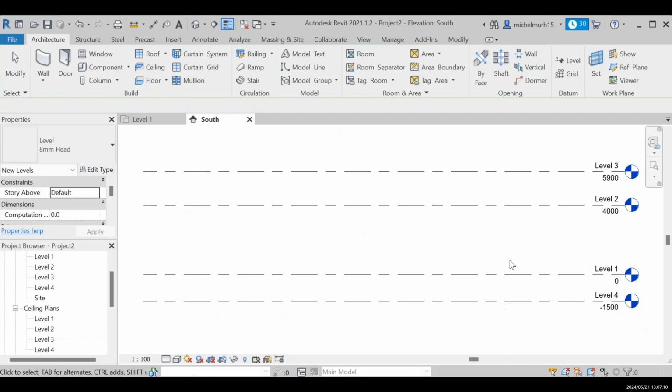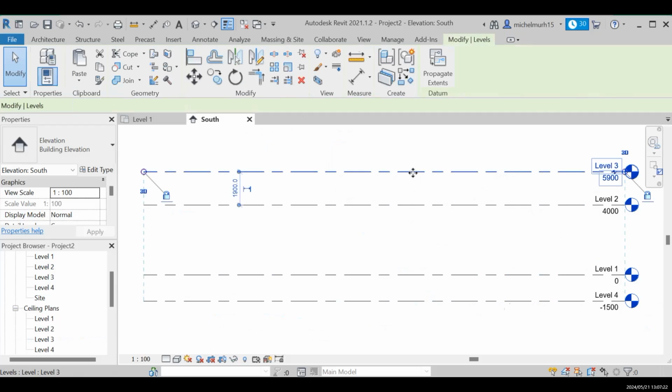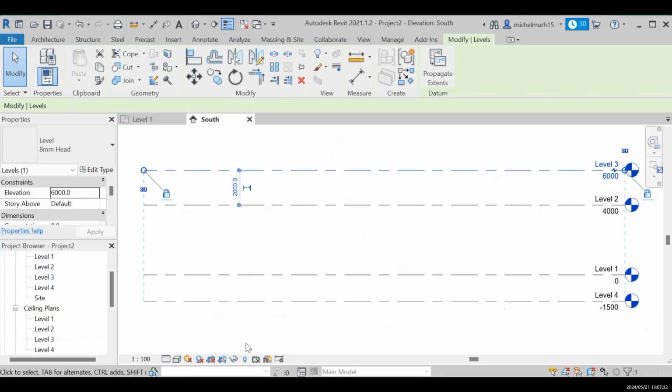If you have any specific value for the elevation, like for the first one, because I just picked them randomly, I didn't consider any value here, right? So if I change the value, just press on one line here, and I'm going to use 2000 for all of them. And this one also, I'm going to use the same value of 2000.